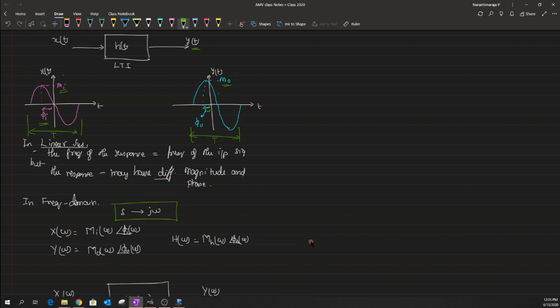The sigma in general defines the natural response part, and to study the frequency response we focus more on the steady state response rather than the transient response. So we define the sigma, or the real value of this s term, to be equal to 0. I hope that is clear.